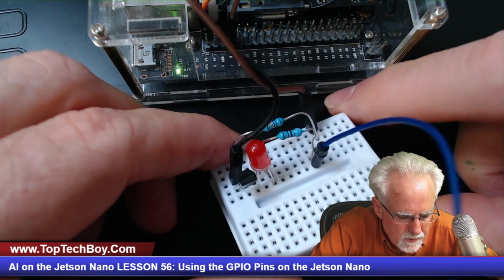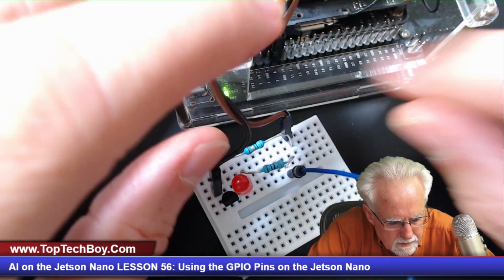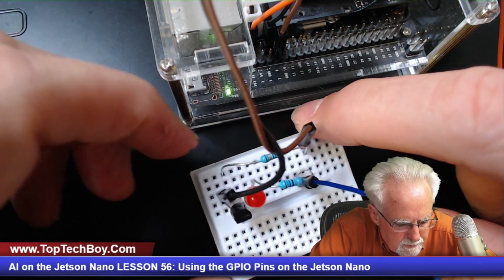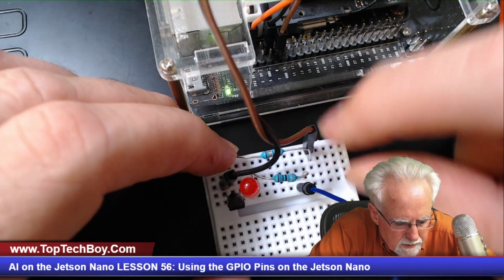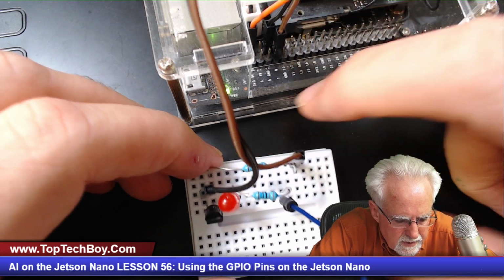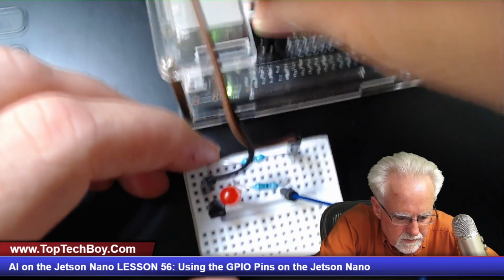Okay, so I've got the emitter to ground. The emitter is in ground. Okay, that's really good. And then my base pin, I've got hooked through a 10K resistor, and then that goes to pin 7, and then I'm powering everything with pin 2.